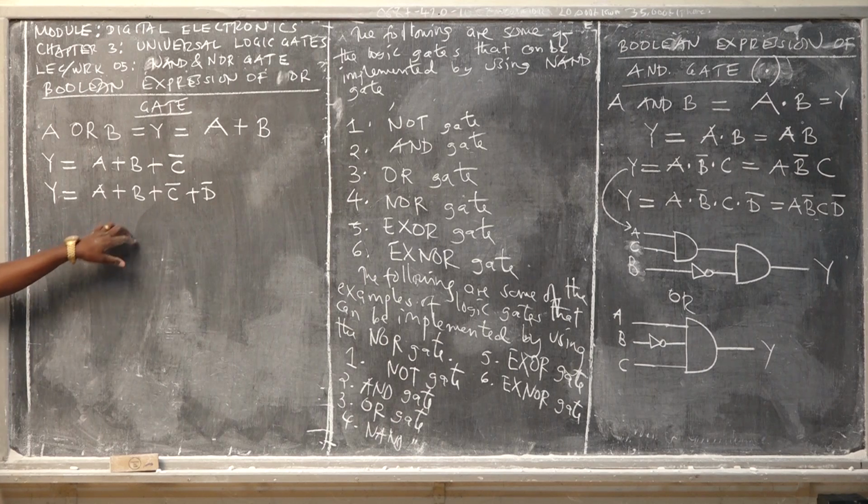If you're using the OR gate of 3 inputs, how many OR gates are we going to have? 2. Are you sure that's 2? If you're using 3 input OR gates, then you are going to have 6 inputs, while there you have only 4. So it means that you don't have an option to use 3 input OR gates only. You may use one 3 input OR gate and one 2 input OR gate.